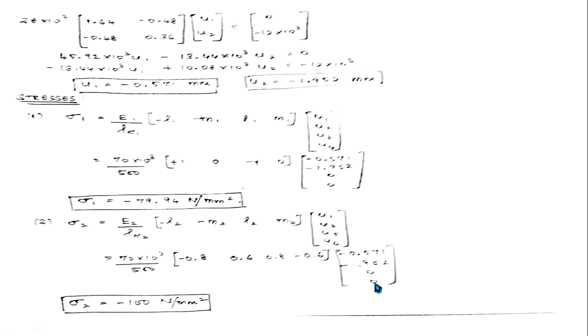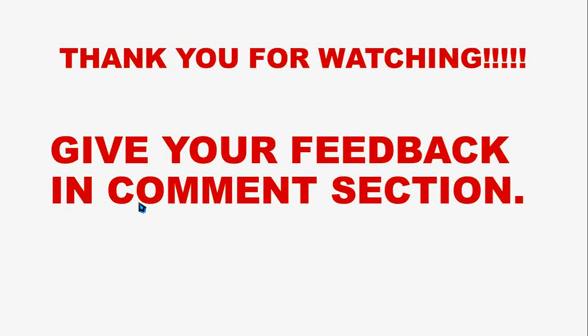As usual, substitute everything and multiply these two. It is 1 cross 4 and this is 4 cross 1. If you multiply, you will get your final 1 cross 1 element, which is minus 100. If you have minus, then it is a compressive stress. If you have plus, you can write it. It's not necessary, but when we have a negative stress value, call it a compressive stress.